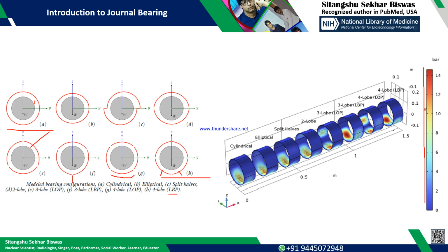If it is a rigid coupling, then the motor's top non-driving thrust bearing design capacity should be very high. To avoid this, the coupling is flexible, because there will be a slight lift when the oil film is generated. So the coupling between the prime mover and the pump is a flexible coupling. Okay, and that load is taken care of by the pump top side thrust pad.